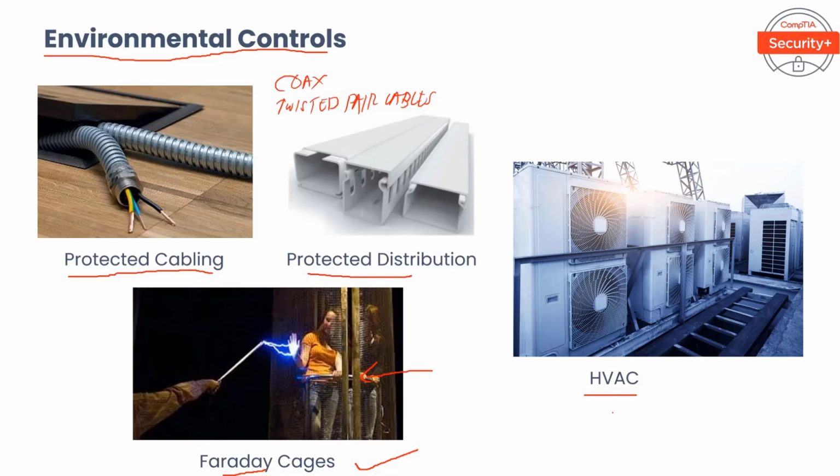When monitoring an HVAC system, keep in mind that overcooling causes condensation in equipment, and too dry an environment leads to excessive static. You need to monitor the area for hot spots and cold spots, ensuring that you don't have one area that is frigid cold under a vent and hot elsewhere. When water or drain pipes are located above facilities, it is important to ensure that upper floor drains do not clog. One solution is to use rubberized floors above the data centers or server rooms. Above all else, timely air conditioning maintenance is required.